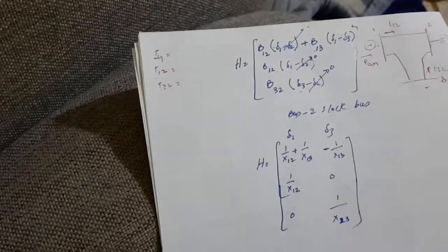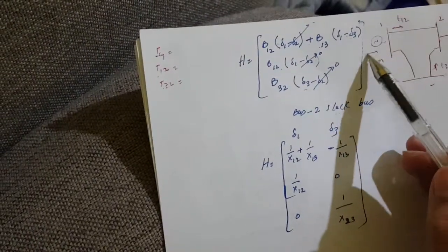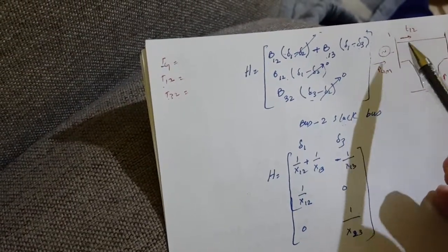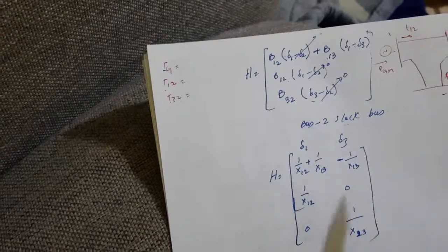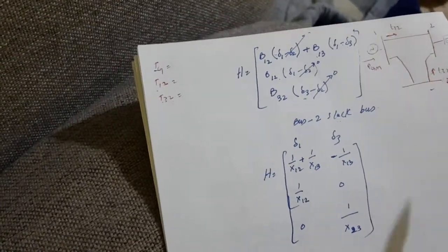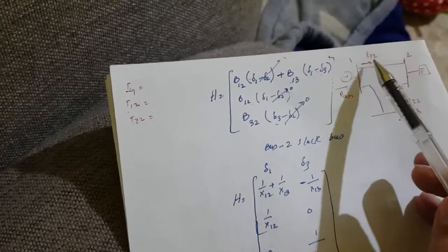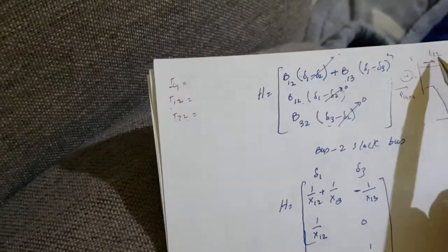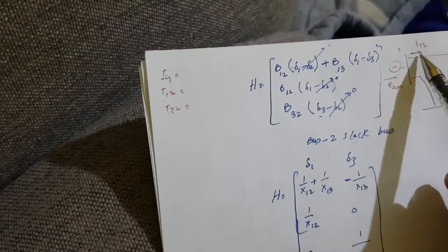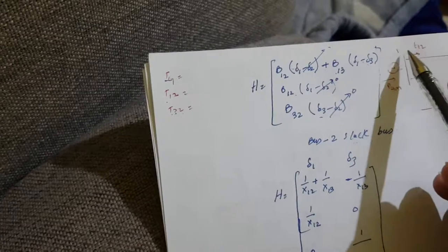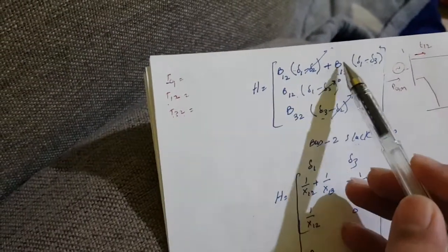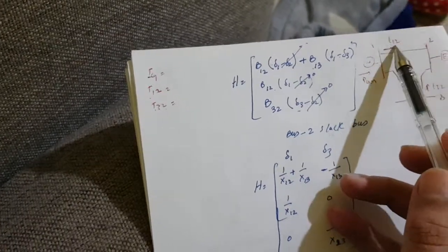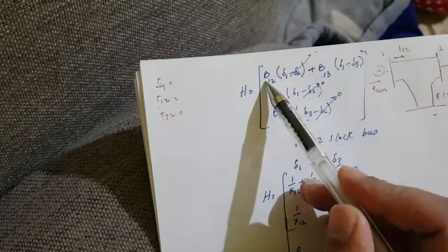So all of the questions you have to find in the same way. If there is a generator, then you have to take care of the buses feeding from that generator, 1 2 and 1 3. One more important point in some of the questions is this arrow sign. For example, here it is given t1 to the value, but the arrow is from 2 to 1. When the arrow is reversed, then you have to make the minus sign here.